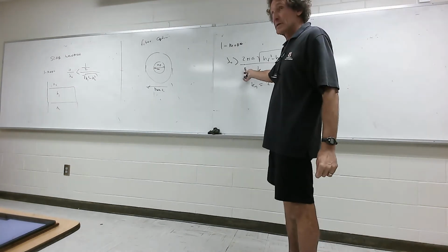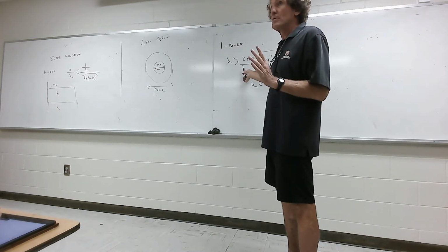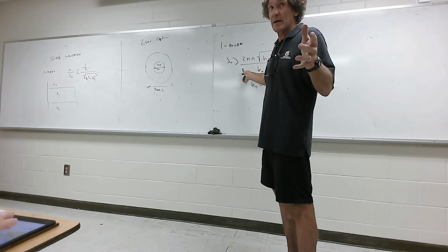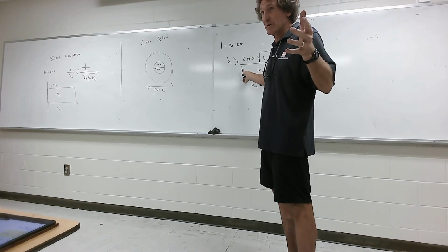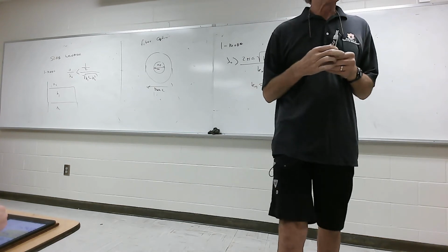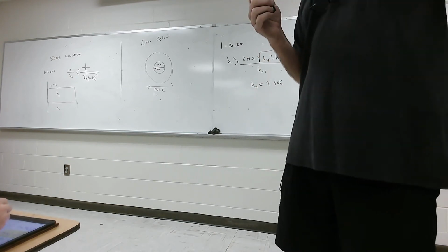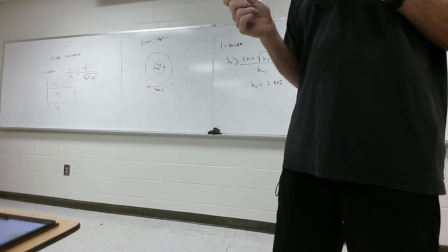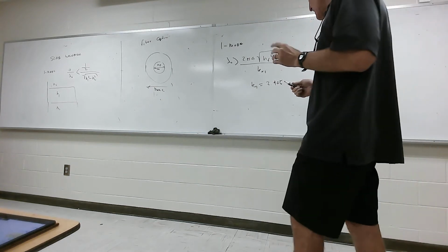Now, I'm going to explain something about this. If you meet this condition, you have only one mode propagating. That's what you want. It's telling you how to figure out what frequencies you can propagate. With most of this stuff, because we're talking about optical fiber, they talk about light in terms of a wavelength, not in terms of a frequency. Y'all follow me on this class? It'll be a wavelength of some laser light source.